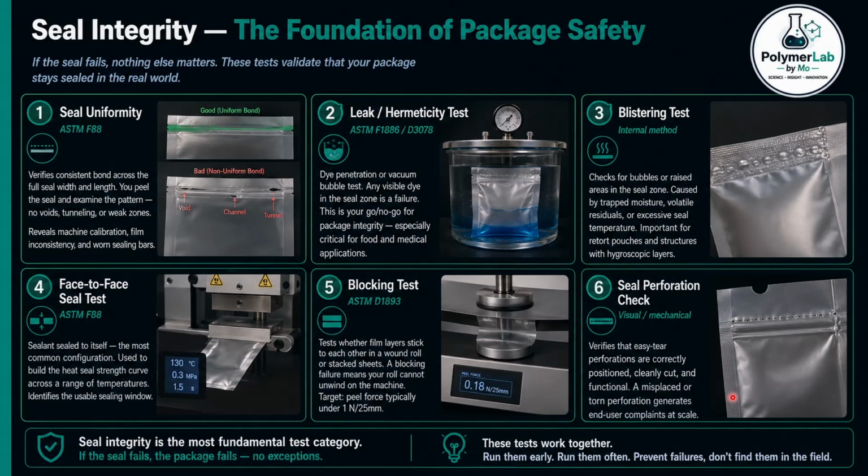Perforation check. Every easy-tear feature on a package, tear notches, zip strips, perforated openings, must be verified for position, cleanliness, and function. A perforation that tears in the wrong direction or requires scissors generates end-user complaints at scale.